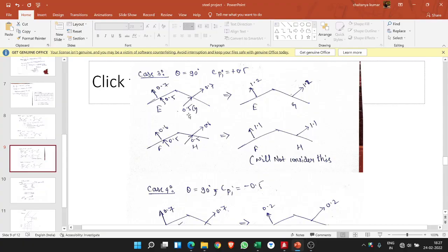So it will have the same pressure coefficients on both sides. If you write opposite values, the professor will think you are making a mistake just by looking at the figure. So keep in mind that when the wind is hitting at 90 degrees, in any case, it will be the same on both sides.